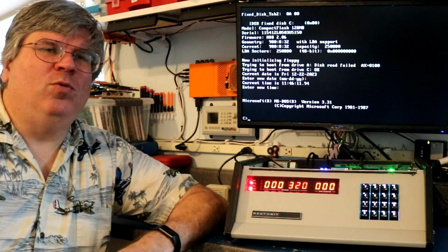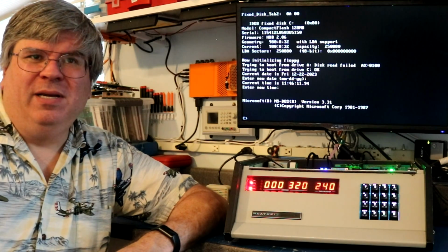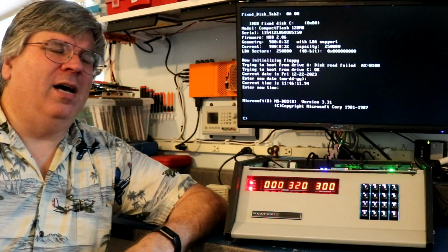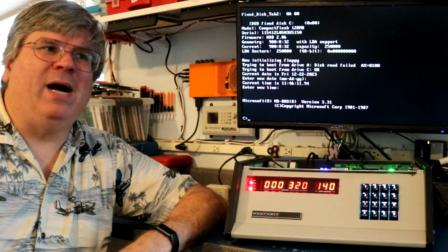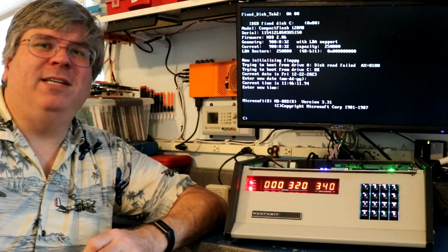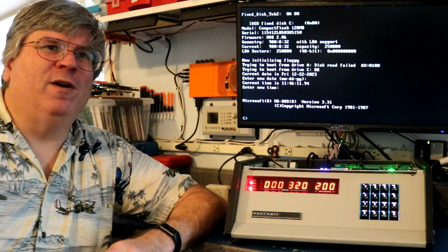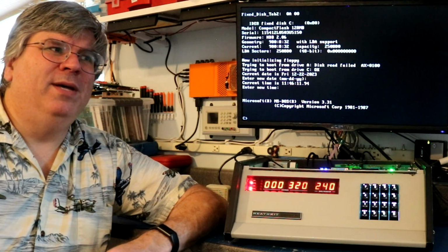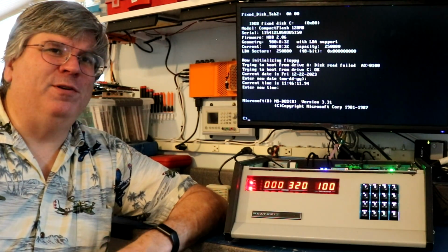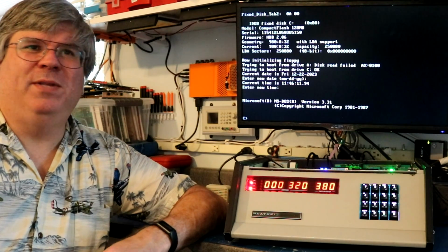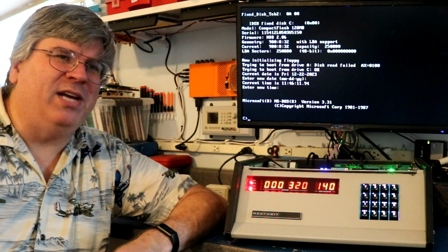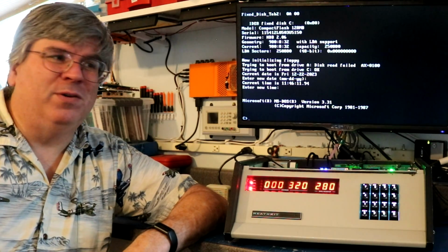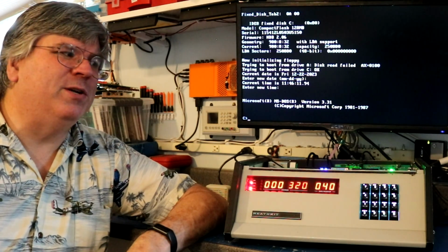However, they're built in a way that is not identical to the IBM PC. In a lot of ways, it's done better, using a better mechanism for I/O addressing. But because it's different, it's not fully hardware compatible with the PC. Some early PC software would assume the existence of that timer chip at its specific port address, or the interrupt controller at its port address, etc. They would make assumptions on that. You might have even programmed the DMA controller directly if you wanted to do high performance memory transfers.